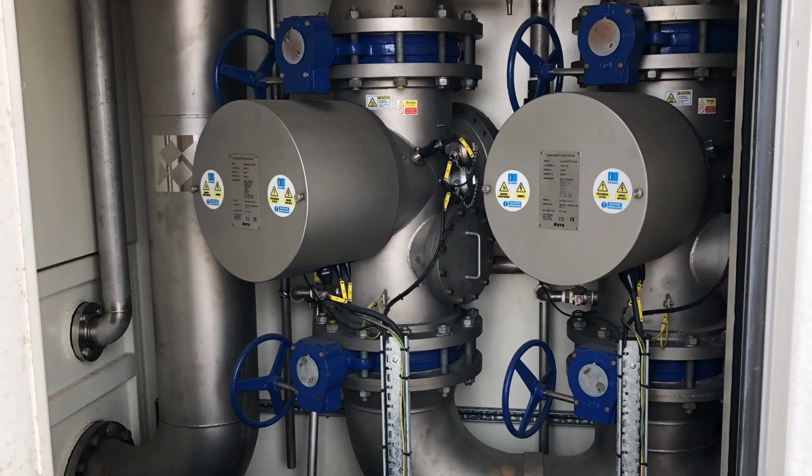However, I knew that if I was successfully generating hydroxyl radicals, then we should also see some hydrogen peroxide being generated. Hydrogen peroxide is relatively easy to detect with a handheld kit. So I flooded one reactor with field water and then shut off the UV lamps. I took a sample of the inlet water before starting, and then I isolated both valves to the reactor so that there was no flow through the reactor.